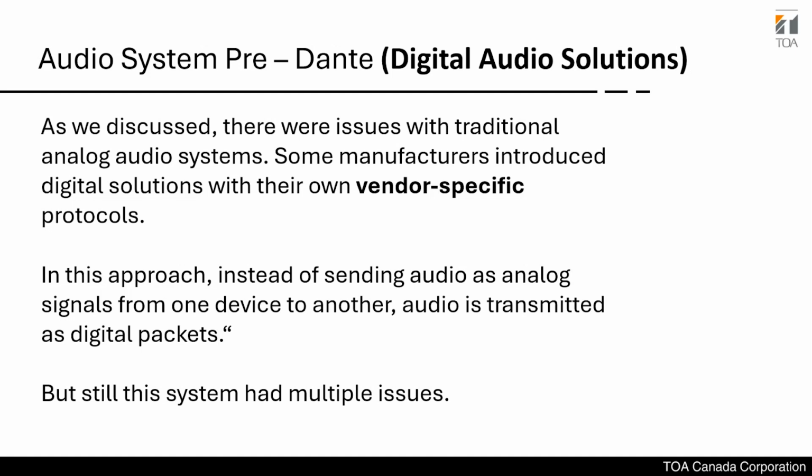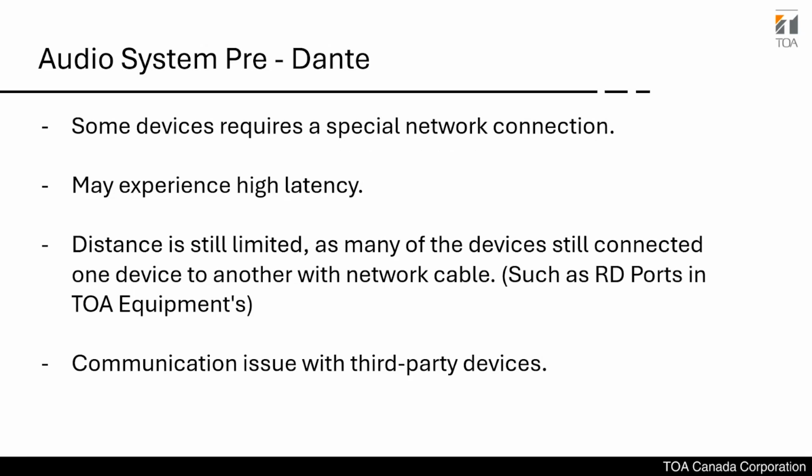So in this approach, instead of sending an audio signal as an analog signal from one device to another device, audio is transmitted as digital packets. But still, this system had some issues. Some devices require special network connections. Even when they came to digital, sometimes they needed a managed switch. Sometimes they just wanted a switch which can work with audio only. They don't want to share this switch with anyone else. If we share third party devices, or if we share something else, there's always an issue with the system.